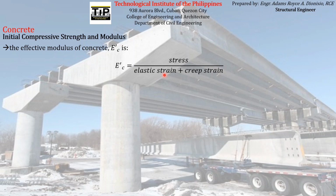But if the material will be supporting that load for a longer period of time, it will eventually experience an additional strain due to that sustained load, which is called creep strain. So the strain that comes from supporting the load for a longer period of time is what we call creep strain. Elastic strain is a strain experienced by the material immediately after you apply the load. So you just add those two, and then divide the stress by them, so you can find the effective modulus of elasticity.